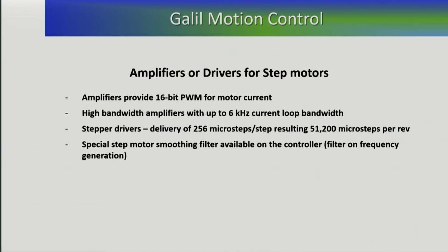If not, instead of 10-bit PWM, look at something that offers 16 bits or 12 bits or 14 bits of PWM. The higher the resolution, the quantization step of current from one current level to the next current level is going to be better controlled and it's going to be smoother. So you look at that and say, can I get a higher resolution on my PWM?